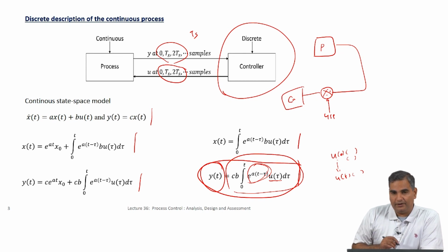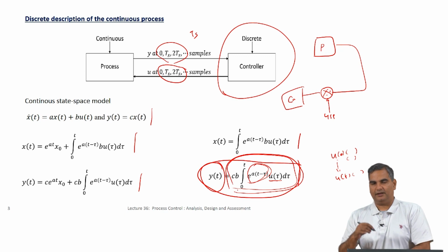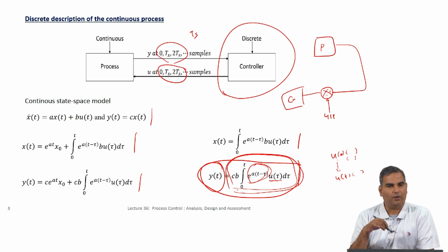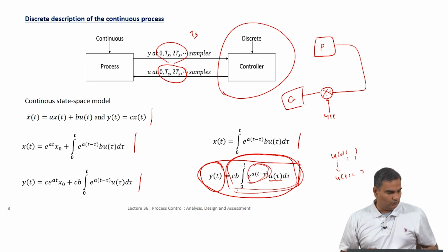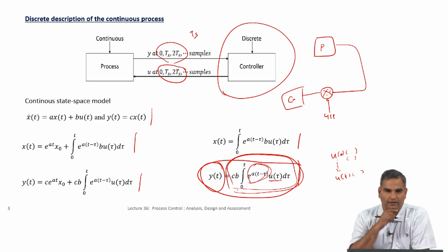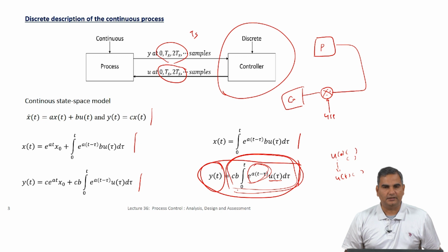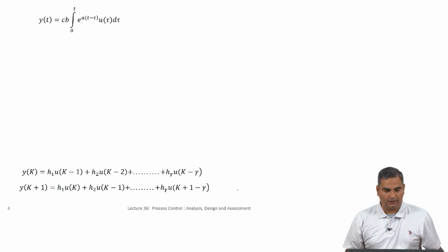Okay. So, this is an important idea to start thinking about. Now, from a model predictive control viewpoint, what we are saying is that this output I can now directly write as a function of these inputs. Remember the question we asked: if I have a model and a control input plan, how would that relate to the actual output values? That is related through a model like this. The only thing is, this model is in the continuous domain, whereas what we are interested in is deriving a model in the discrete domain, because most of the formulation and the solution are in the discrete domain.